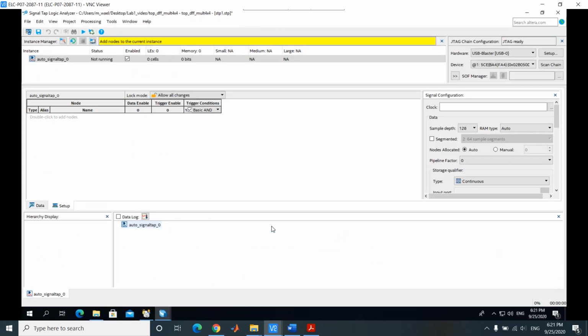Currently what you are seeing is that our program runs successfully, and now it is on the FPGA, but you can't see the result. So the proper method to see the result is by using the SignalTap logic analyzer. SignalTap logic analyzer works as an oscilloscope. The whole objective of SignalTap is that you can probe any signal in your design and specify certain memory elements inside the FPGA, so it can collect or capture data when certain events happen.